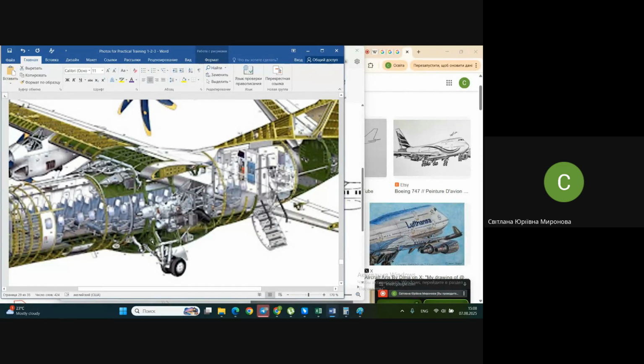It's maybe under the fuselage, over the fuselage, but if you select, for instance, mid-wing, what happens then? Then you have this structure that passes through the passenger cabin, in case you have a passenger airplane. It's completely inappropriate. It can't be like this.